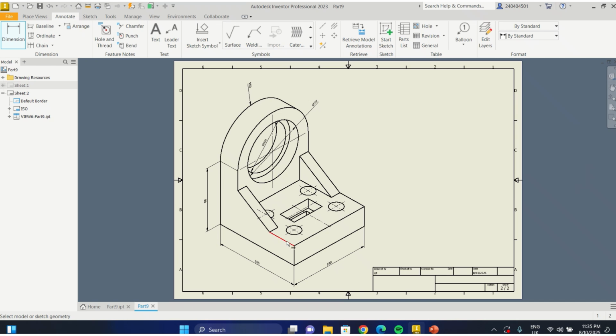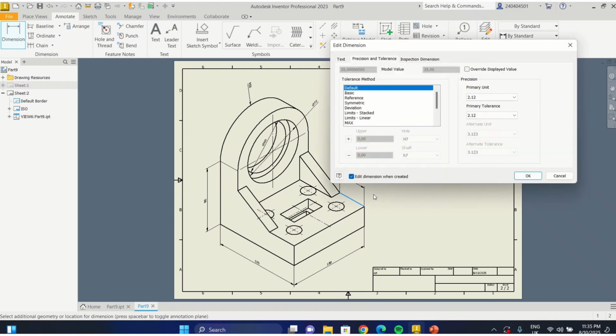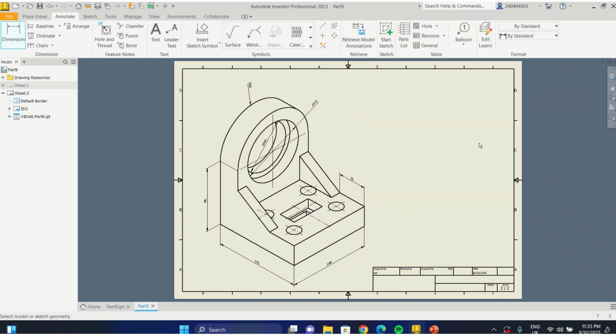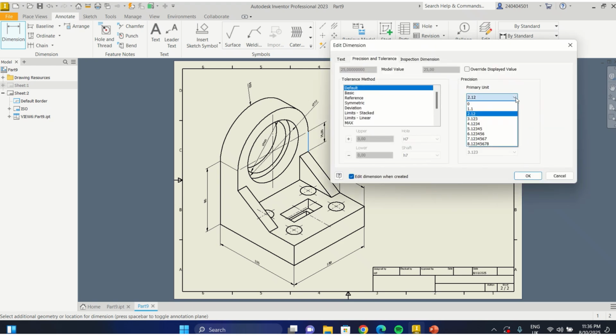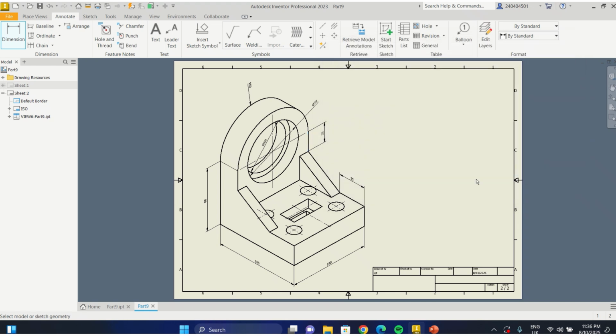You can locate this one too. Okay, let me pick on this other side. Since we know this, I can just do this. I just need to create enough dimensions to describe the geometry of the figure, and at the same time be sure that the dimensions are not overlapping or causing issues with each other. So at least with this and this, we can produce this.